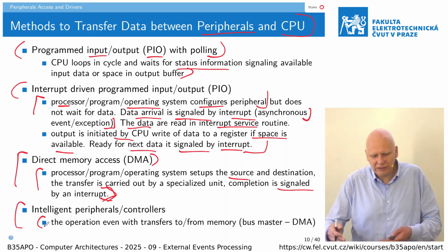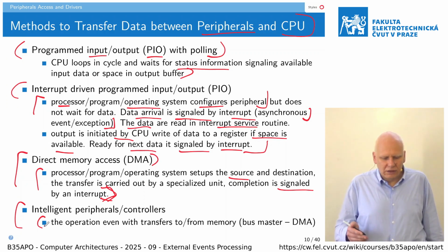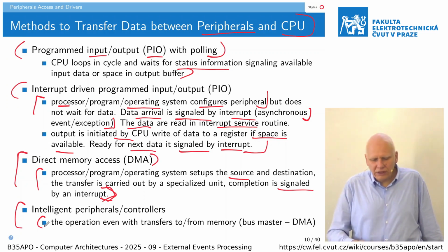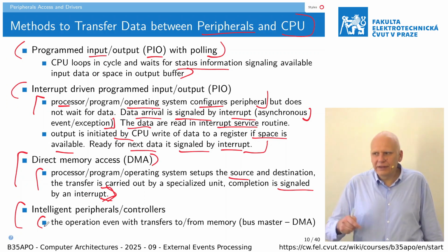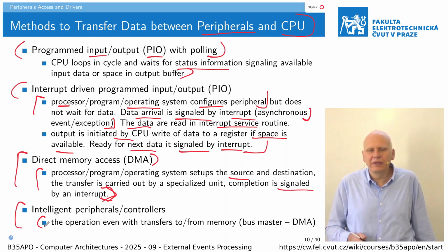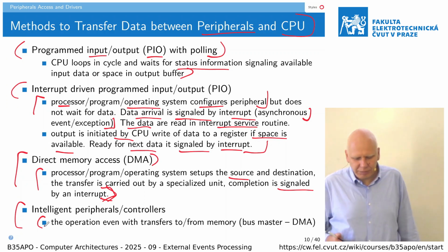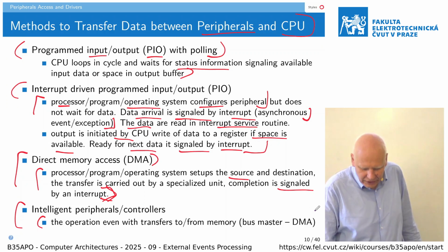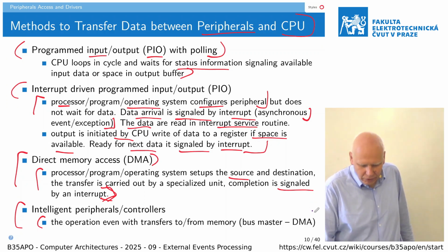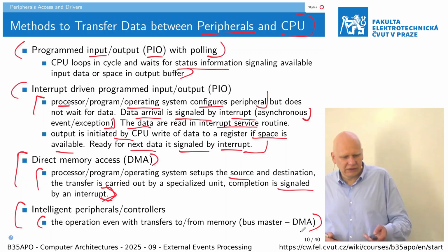You write this stream somewhere to the memory, and the GPU reads the data and commands, and according to this information, it copies other data, for example, between the main memory and the GPU, and computes a 3D scene, and so on. So it is bus-master DMA in this case.